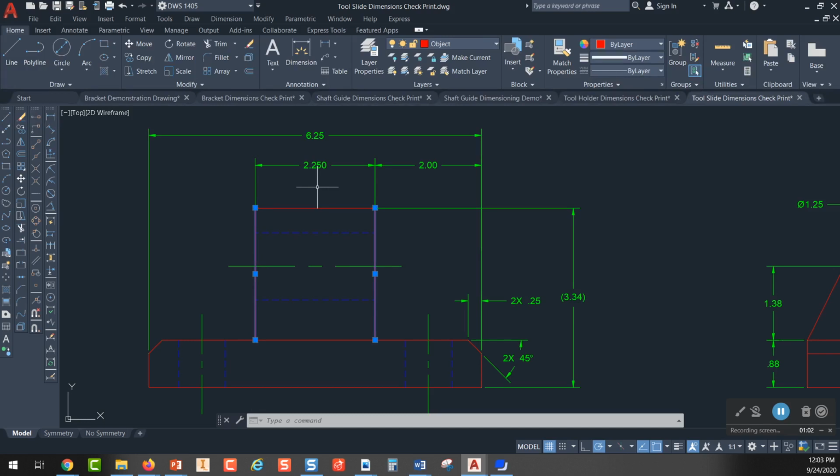So what that would make me think is, if they're tolerancing the width of that piece right there to 3 decimal places, then it may fit into a slot or something, and that slot is toleranced tightly, okay? So you've got to make sure when you put this 2.250 in there that you go to 3 decimal places on that, even though the dimension next to it is 2 decimal places.